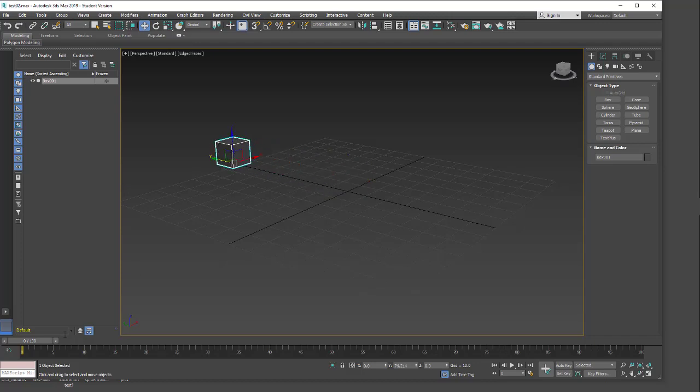So I'm going to move the box back. I'm on frame 0. I'm going to use auto key. Auto key is something you have to be a little careful with when you start off. It's very easy to think that you're doing animation and then later realize that you've recorded over your animation because you forgot to use your playhead on your time slider, you forgot to move. With auto key, you have to be careful. You have to make sure you have your time slider on the correct frame. When people are starting out with animation, this becomes a little dangerous.